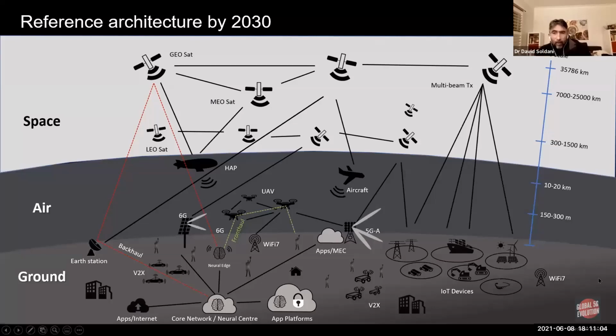If you look at Wi-Fi, even Wi-Fi 7, 6, the cell range is extremely small, because if you want to enjoy the bandwidth, you need to transmit at least at a 160 megahertz band, and that won't allow you to have more than 50 meters range. Therefore, the deployment of those systems will be extremely local, on campus,